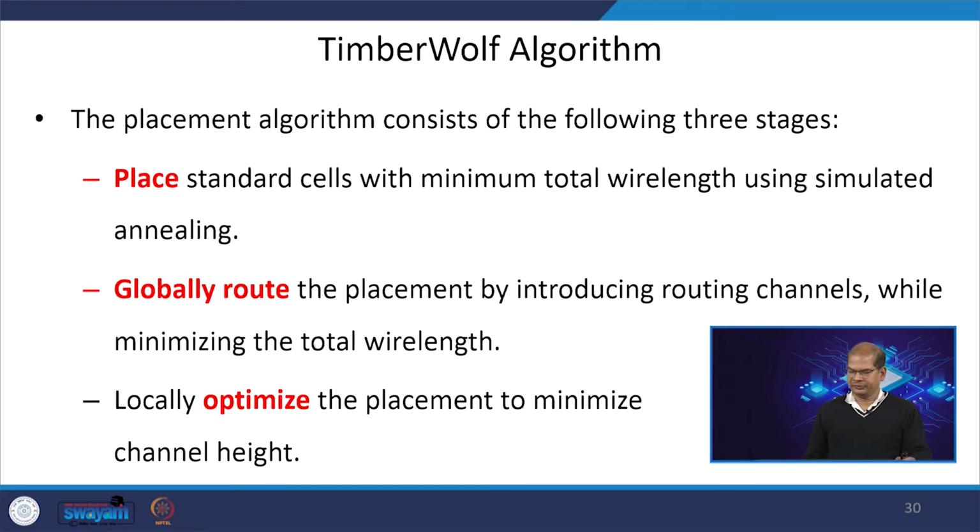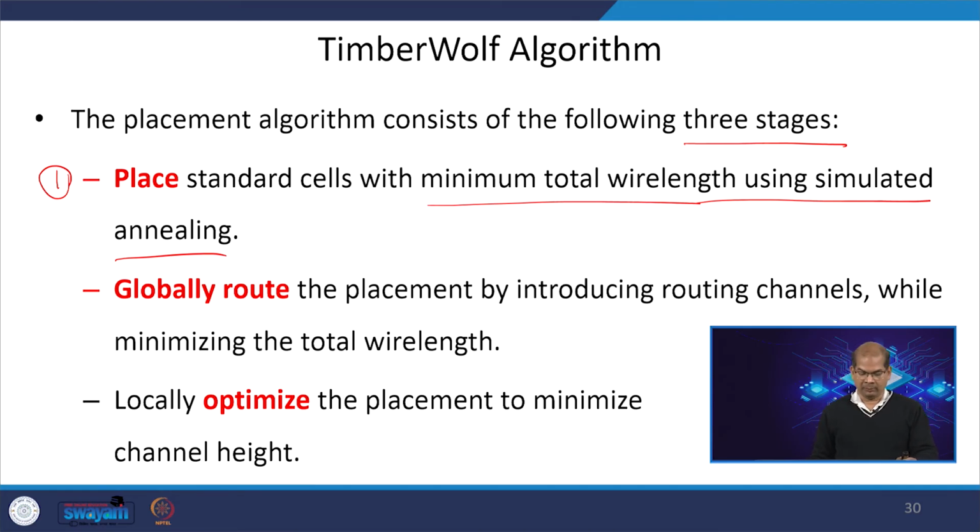It has 3 steps. The first step is the placement of the standard cells with minimum total wirelength using the simulated annealing approach.